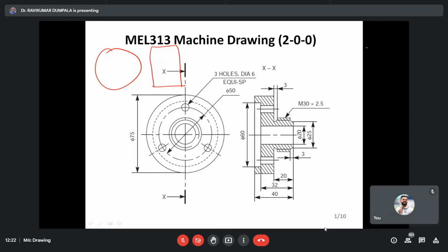Okay, so they don't mention it in microns, because the casting they produce has a width that is also approximately this much. Suppose the width is 40 mm, they produce 41 mm or something. Otherwise, tolerances will be in terms of microns. On the component side, it's closer at the final stage. Tolerances will be very, very close. So it depends again on the functional requirement: 20 microns, 10 microns, 2 microns.